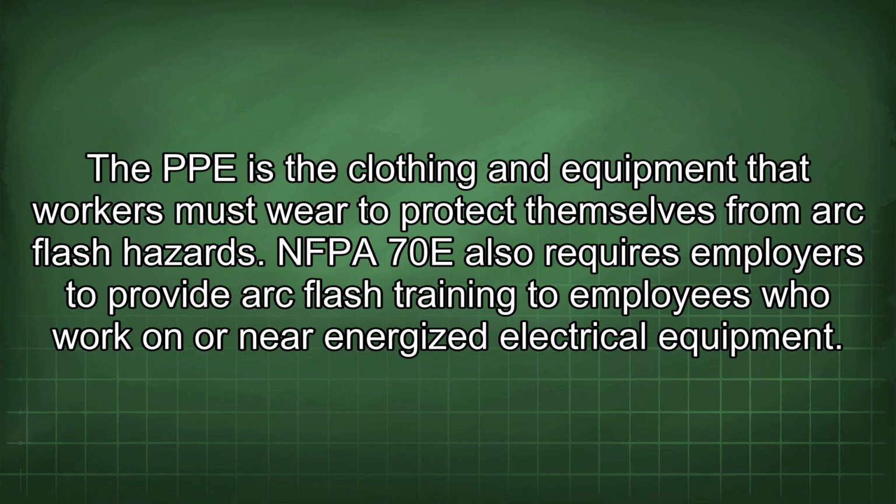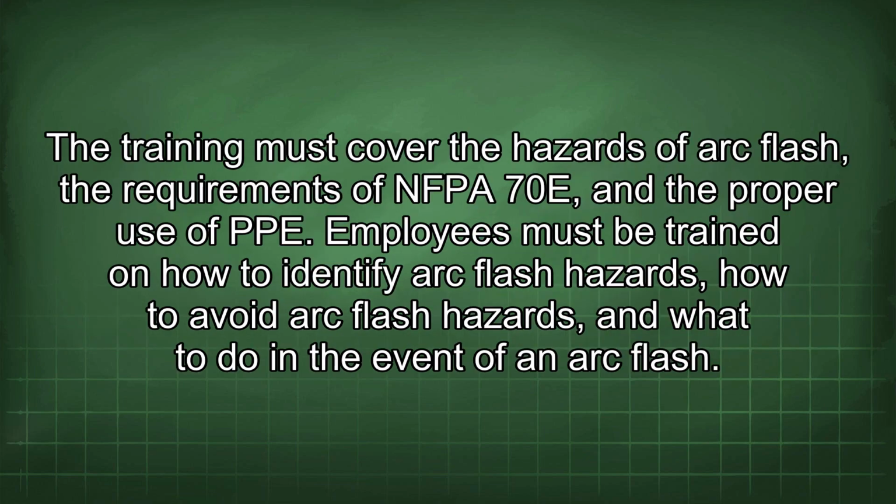NFPA 70E also requires employers to provide arc flash training to employees who work on or near energized electrical equipment. The training must cover the hazards of arc flash, the requirements of NFPA 70E, and the proper use of PPE. Employees must be trained on how to identify arc flash hazards, how to avoid arc flash hazards, and what to do in the event of an arc flash.